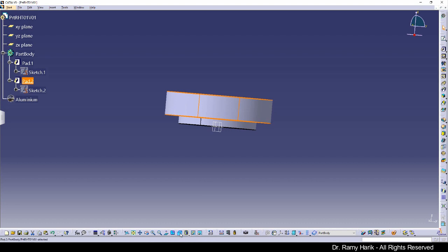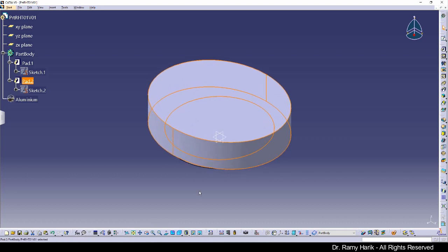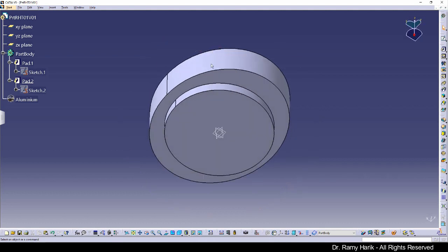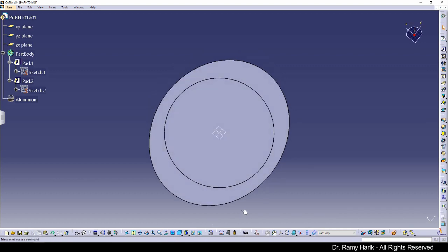and I'm going to click isometric view, and I'm going to fit all in so that it is clear for everyone. Now you are being asked to create a sketch. Rotate the part and select the lower face. So we're going to rotate our part. We could have selected the part, and you could click on the normal to plane,